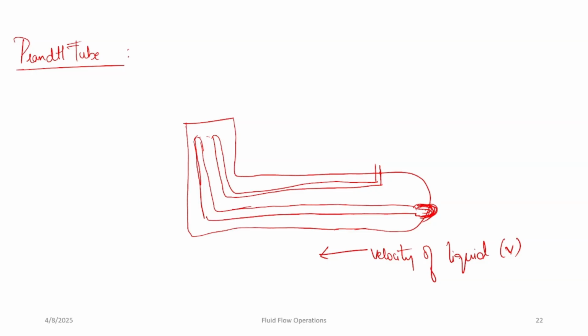Okay, so then you'll be needing corrections for shock waves that can be applied to allow it for high speed craft or high speed aircraft. Okay, so if the tubes become clogged or pinched, the resulting pressure at the transducer is not the total and static pressures of the external flow. Okay, so the transducer output is then used to calculate a velocity that is not the actual velocity of the flow. Okay, so these are the issues that we have with pitot tubes.